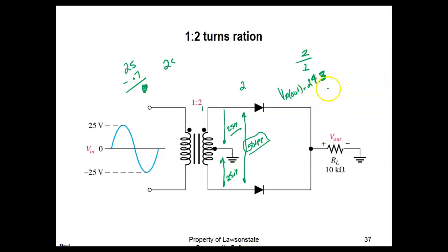And then this is V peak out, and then we'd use V peak over pi, right? So you've got to be careful on this too. So notice what they're giving here. They're not giving us RMS. They're giving us volts peak, which would be 50 volts peak to peak. That's one of the times when my brain went dead. So y'all see that a few times.